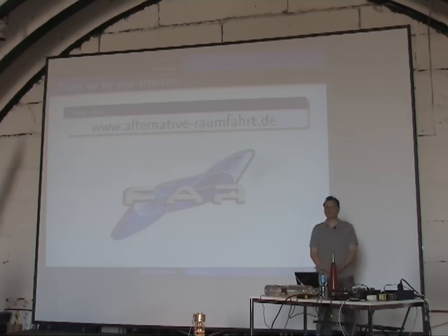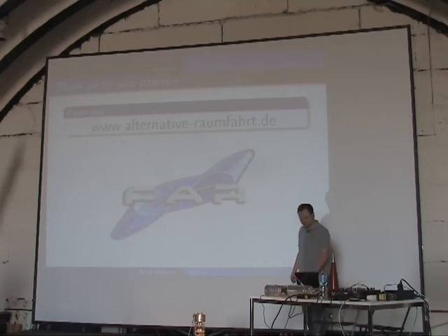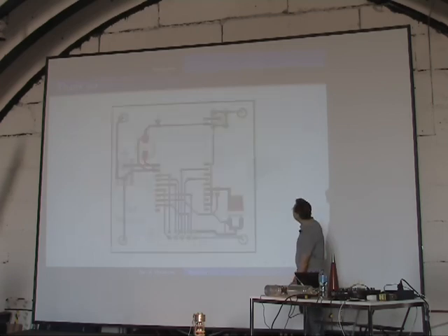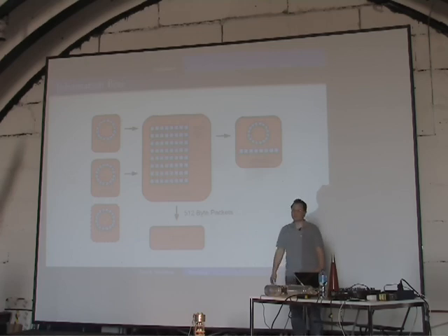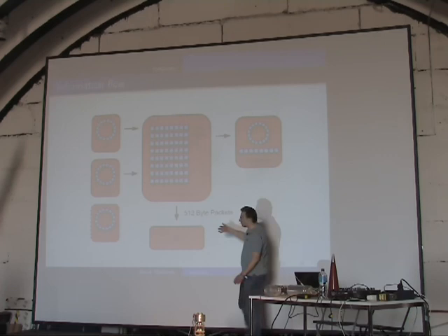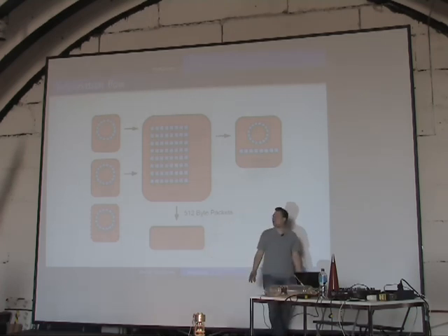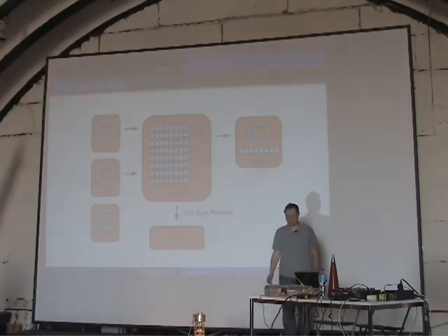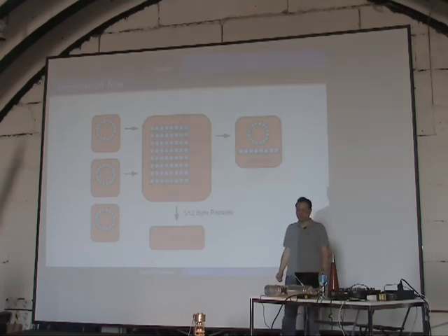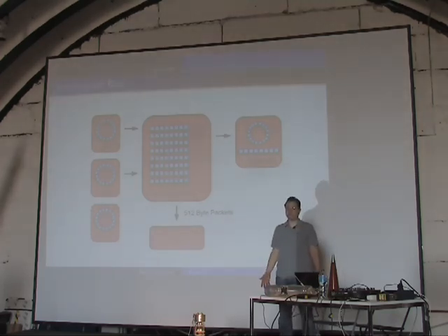Thank you. Is the software programmed in Spin or in assembler? Both. The software you saw just before is all programmed in assembler. It has to be very fast, especially the routines that write to the SD card. This could not be done in Spin, it's just too slow. Everything is programmed in assembler, but of course the main program that initializes the objects is done in Spin. Yes, but everything else is done in assembler.